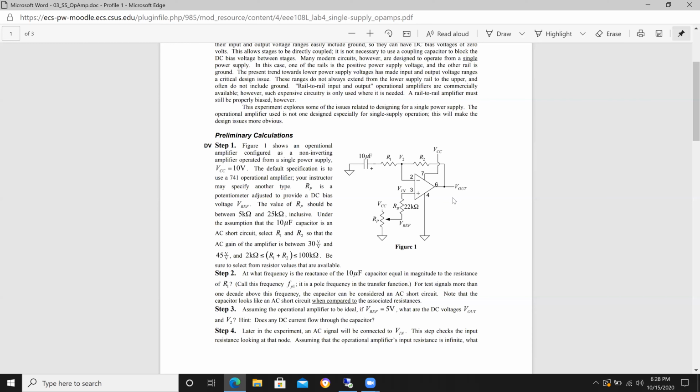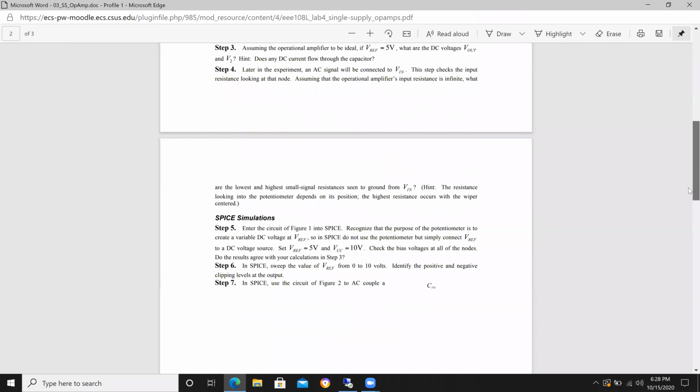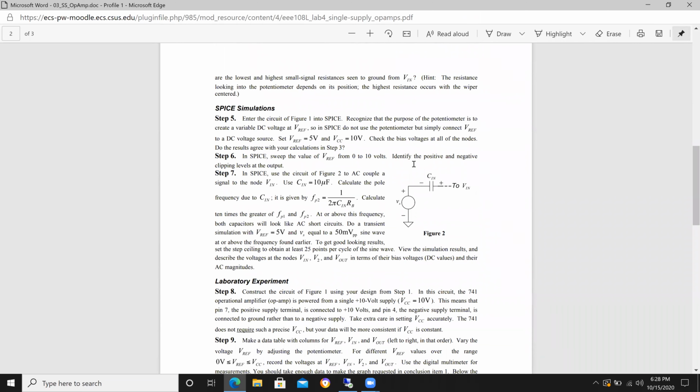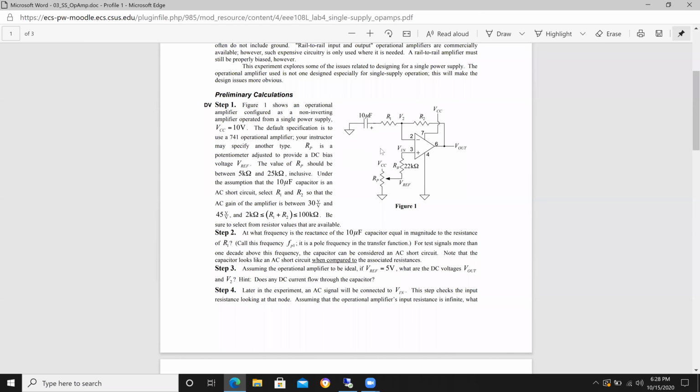You might be asking yourself, well, first of all, you're going to have that capacitor right here, right? And I wish I would have drawn it up here, but you're going to have this one right here feeding a signal in here. Well, first of all, in order to get a signal across that capacitor and coming into VN, it's got to be high enough frequency, right? In order for the signal to couple through the capacitor.